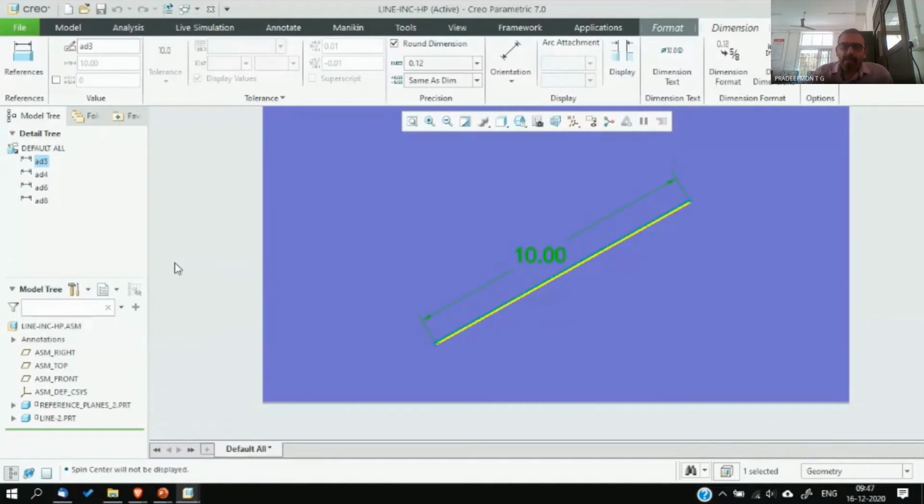When we project these endpoints, the projectors, as well as the actual object and the front view, create a rectangle itself, in which the opposite sides are always equal. So since the opposite sides are equal, when the length of the actual object is 10 centimeter, the front view will also have 10 centimeter length. So that is the condition.